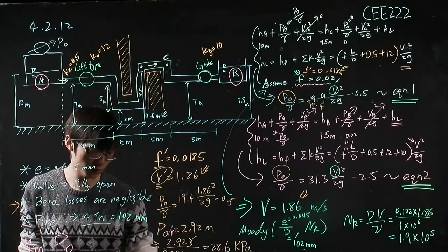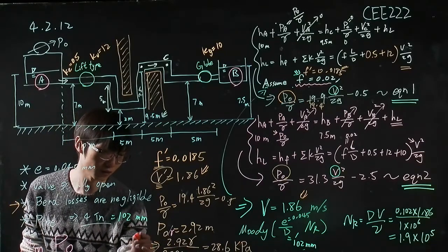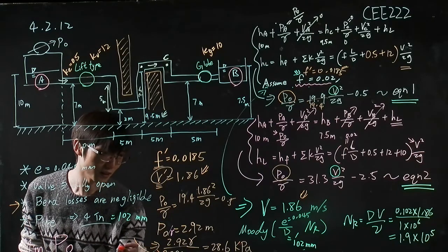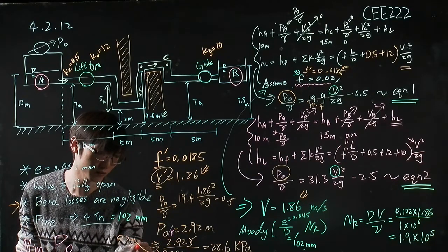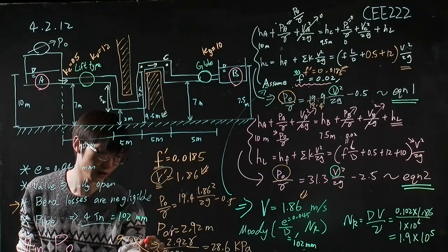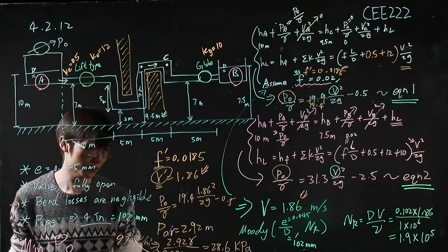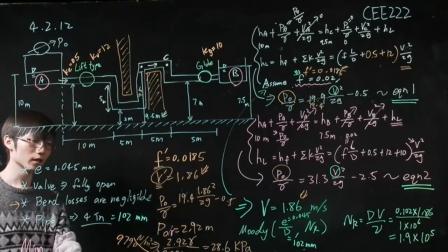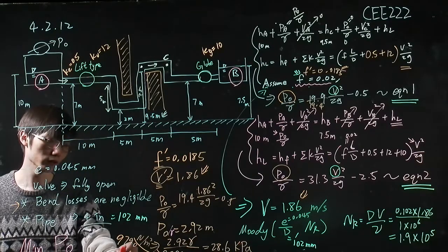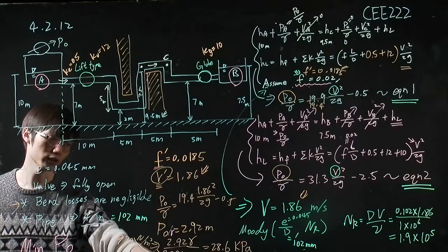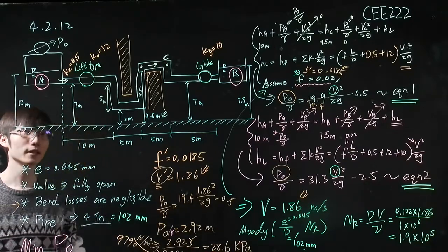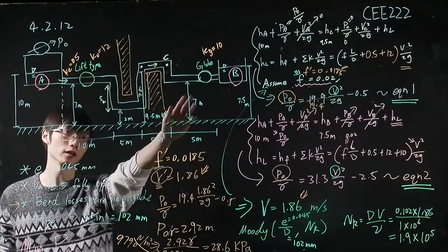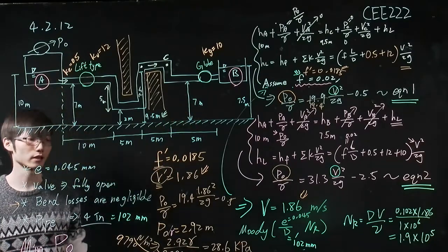Oh, it's too low. You cannot see. So the bottom part of this equation is equal to 9790 N per cubic meter. Okay. So with the unit conversion, we got this final answer, 28.6 kPa for this P naught to ensure the pressure in this pipeline is positive.